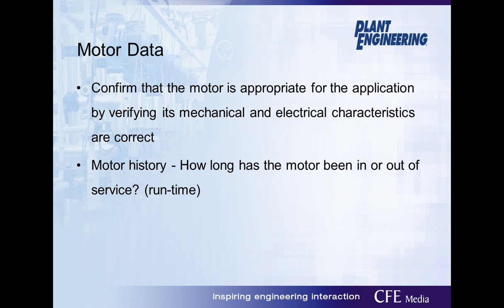One key factor that plays a part in troubleshooting motors is knowing the motor data and the motor's history. When we talk about motor history, we're talking about how long the motor has been in service and how much runtime the motor has encountered. When troubleshooting motors, if you think the motor failed prematurely, then not only do we want to look at the in-service time, but it's also a good idea to know how long the motor was out of service before running.